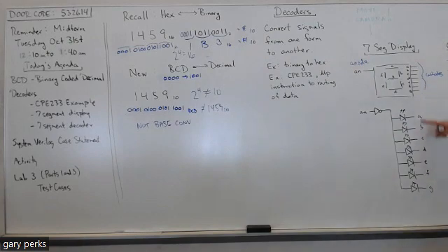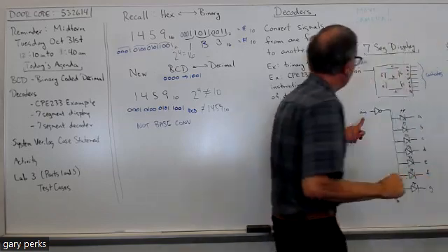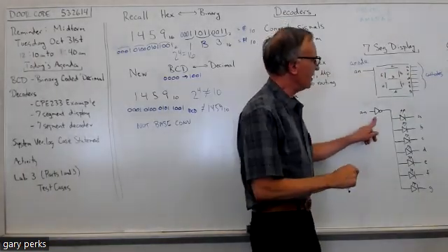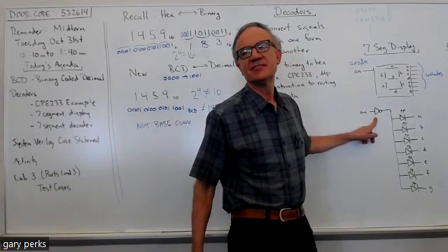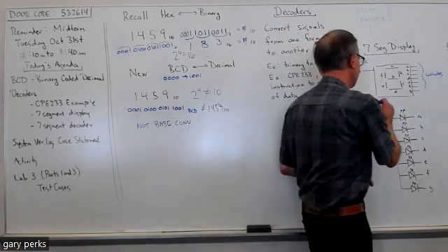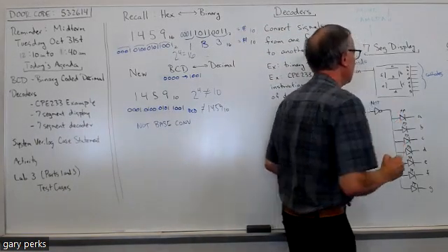Okay, so now this diagram is like a more detailed version of the 7-segment display. Here I'm showing each segment as an LED. LEDs have the diode symbol, which is this arrow with the vertical line, along with two arrows that show that it gives off light when current passes through. So here's the AN input, and then what kind of gate is this? Not gate, right? That's the inverter. I'll explain why that's there coming up.